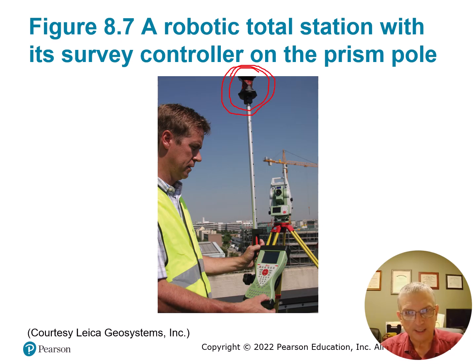It's called a 360 glass or 360 prism, in that it's got those same mirrors set up so that it reflects, but instead of being one-directional like your typical prismatic mirror that you'd set on top of your average rod, which directs it back at the instrument, and you have to make sure that the prism is pointed towards the instrument, a 360 prism is able to do that from anywhere. So you don't have to worry about pointing it towards the instrument.